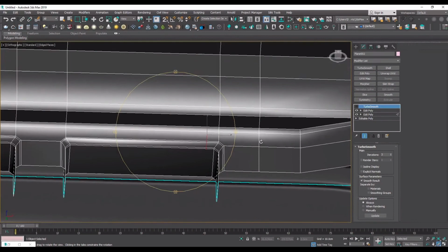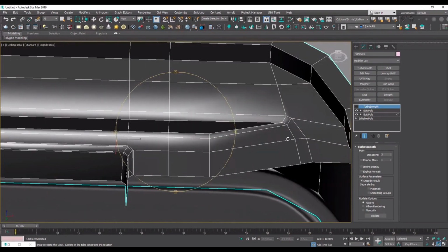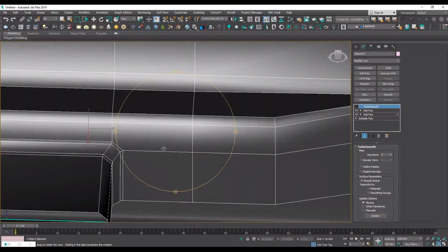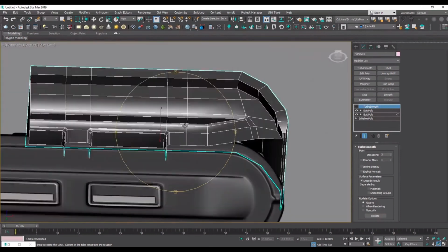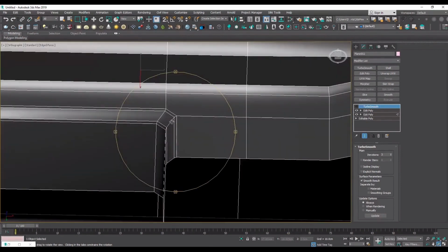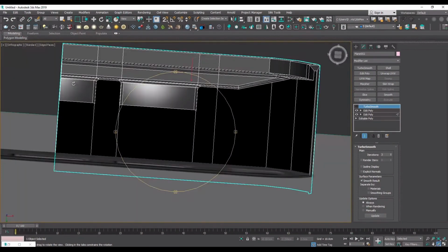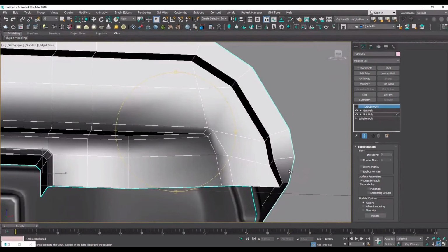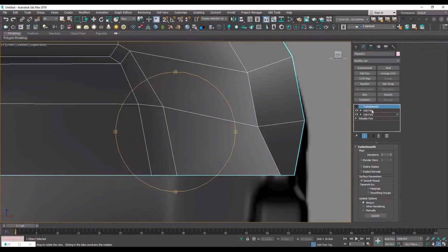And notice I said about the safe margin here, this edge on the middle part. It prevents the shading on the right, or better said, the bending effect on the right, to interfere with our chamfer on the left. You should pay attention that if you just forget about that or overlook this safe margin and first create everything and then try to limit this behavior by adding the edge, you will be getting some major topology issues that then you need to spend some more time tweaking and adjusting.